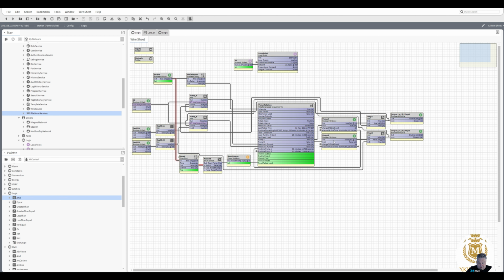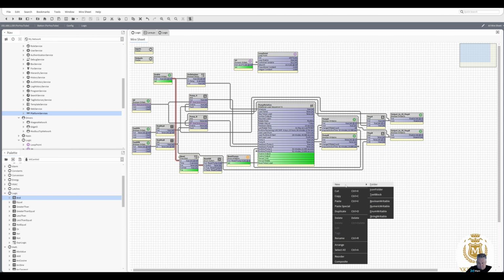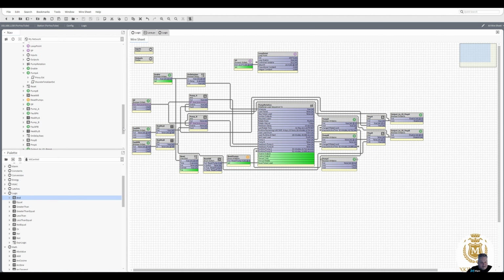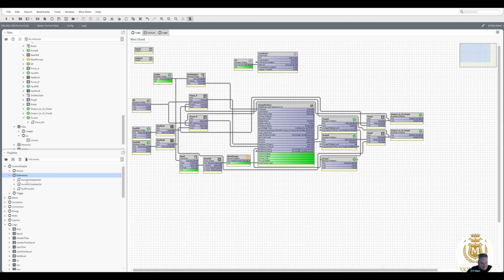Alright, let's add another pump in because I'll show you how to do this change of state. So we'll start with a blank block. Pump. I would normally just copy that, but that's no good to you. This is a learning channel, so you need to know how I've done it. Actions, set that to false. Now I'm going to find that in here, which is there, and I'm going to go to my extensions and a discrete totalizer. I'm going to put that into there. So I've got a discrete totalizer in there now.